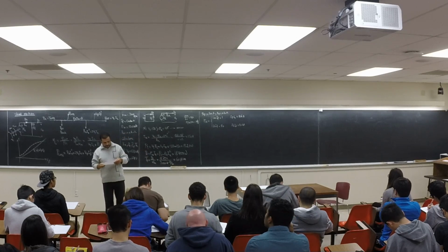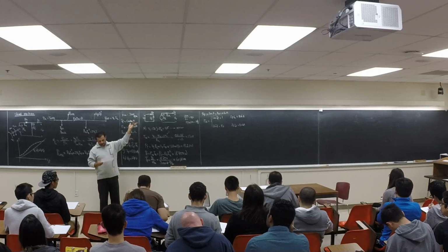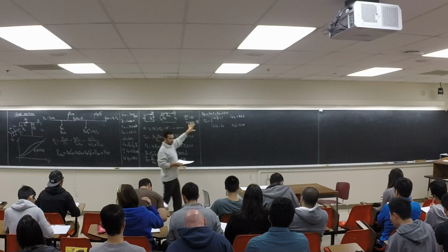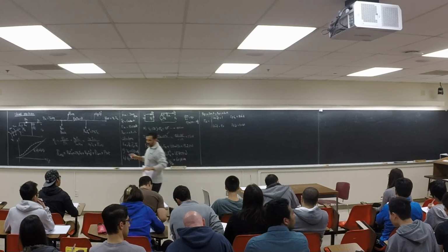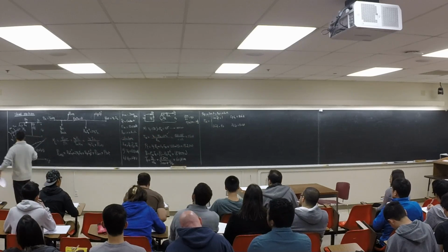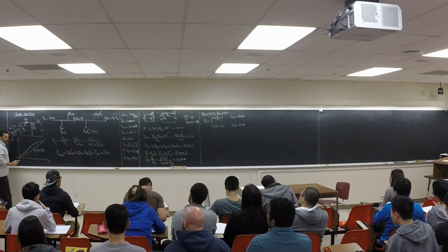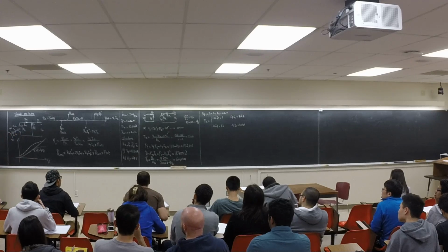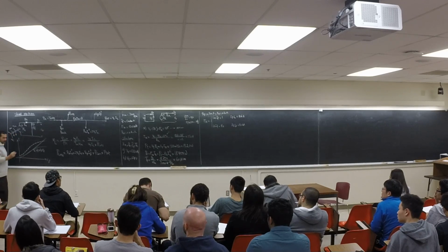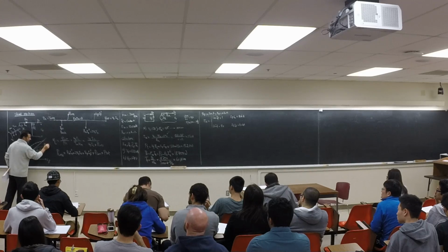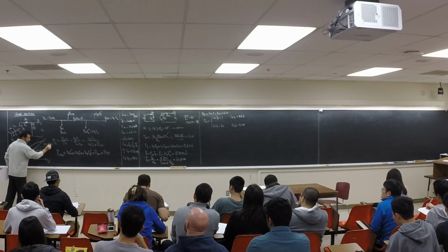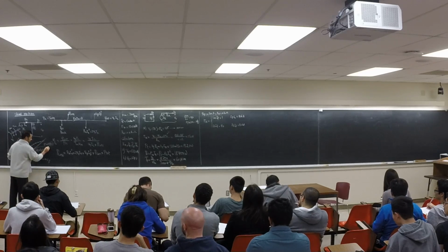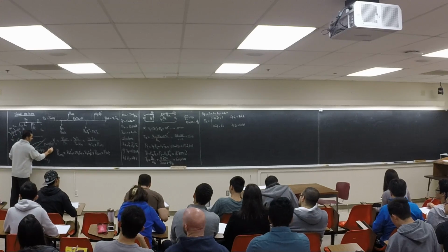Usually it should tell you what speed it is, but here I don't know, whatever speed it is. Usually this happens at a specific speed. Remember, if for example this curve is for 1000 RPM and I reduce the speed of the machine to 800 RPM, the curve is going to be lower. Why? We said E is equal to K flux omega, so for IF, you can say KF IF omega.